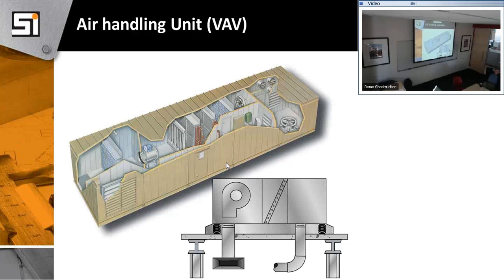So what I'm hearing from you is that within Title 24, more than likely you're going to see more and more of those CO2 sensors. Instead of going by standard square foot and continually dumping 500 in, they're going to look at the CO2 count. That way you can minimize the amount of air coming in, because you can recirculate and cool it, keeping the cool air recirculated versus bringing in, on a day like today, maybe 70-degree air and having to cool it.